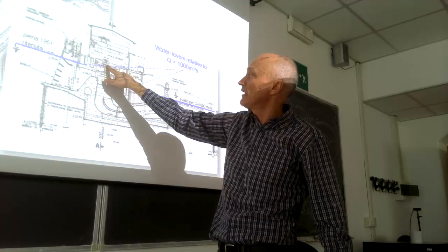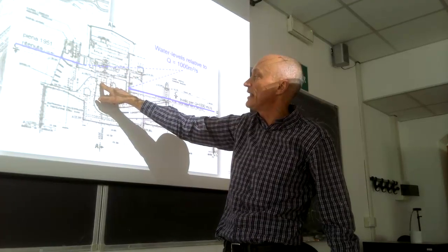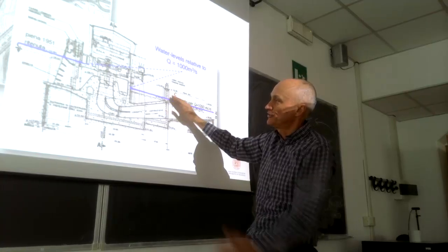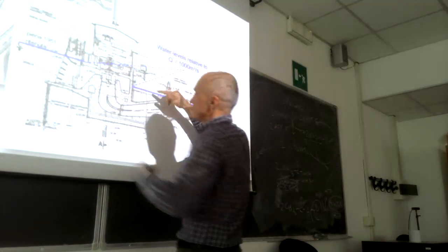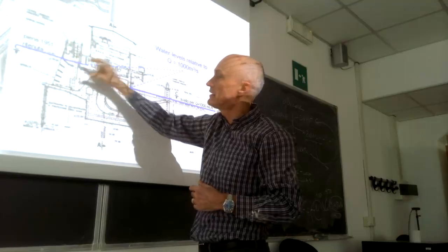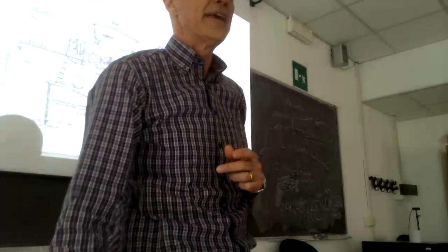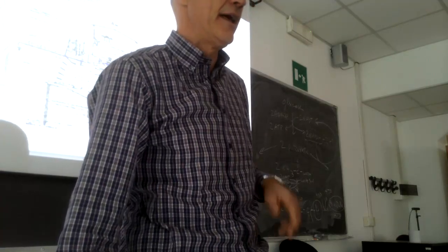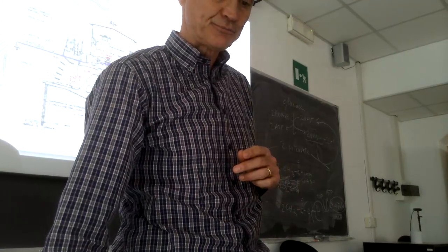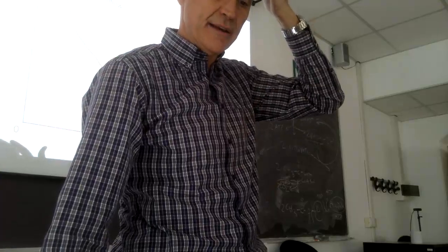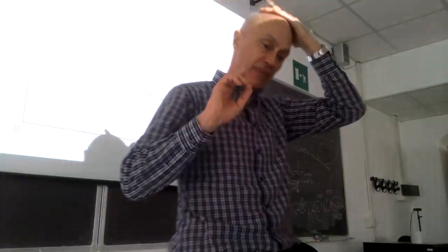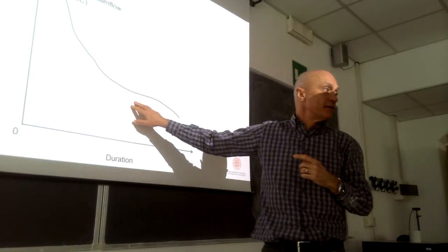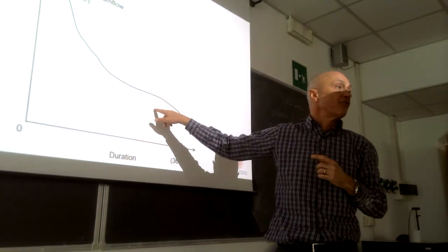Now, what happens? Let's suppose this is the flow duration curve for the natural stream flow of the Po River in that river cross section. Okay? Can we use all this water? No, we cannot. As we said before, there's a maximum discharge that can be used by the turbine, 1,000 cubic meters per second, right?